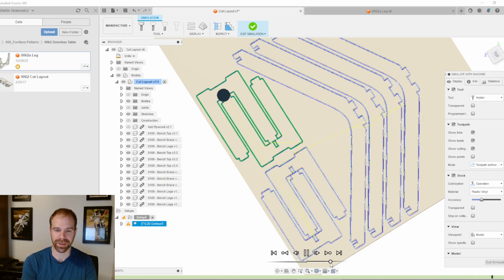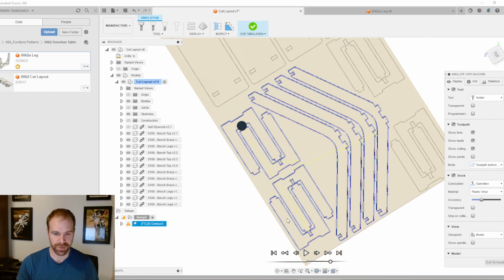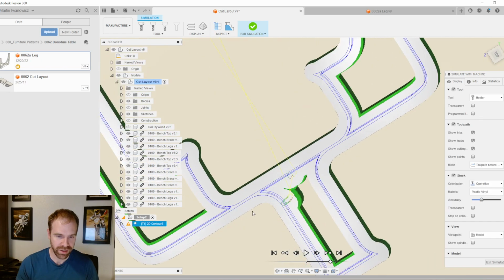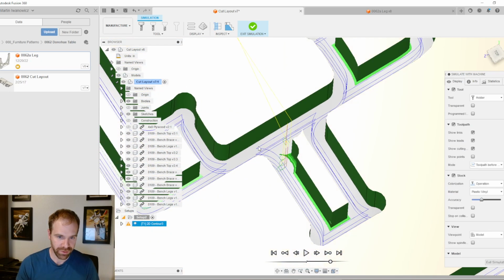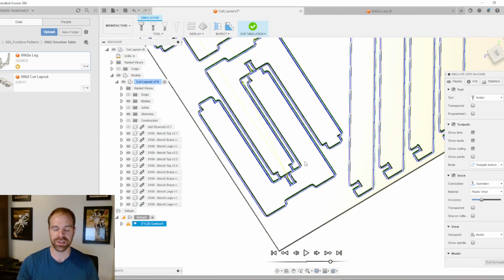Oh yeah, this is something I need to talk about. If you just saw right there, the roughing pass, I'm going to have to do a follow-up video because there just isn't enough time to go over it right now. You can see that the roughing passes here don't go all the way to the next one. What it's doing is the roughing pass would push it into this other part. So this is part of the challenge of doing tool programming and pathing, and there's a little bit of finesse to get this just right.